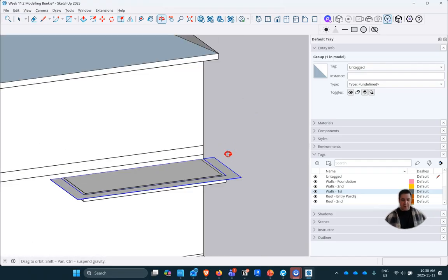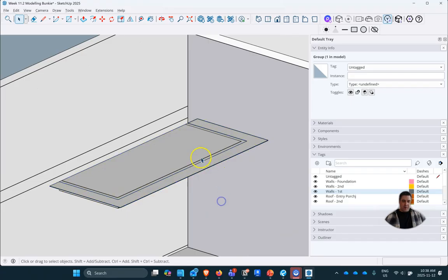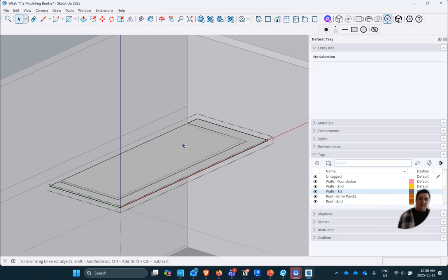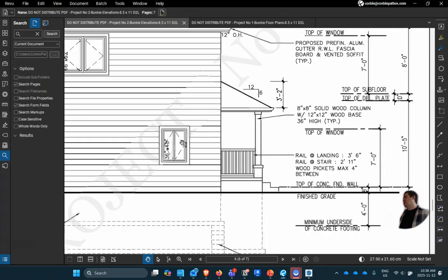So there's our roof. And so let's now work on the pitch. So let's edit our piece here. And so we have a slope of some sort. And I think the normal assumption is it's probably going to be the same, the 5/12, but if you actually look at the drawings, it's not. So we have a 6/12 pitch here. Honestly, I don't know why they decided to do this. I'd probably just keep it the same, but for all intents and purposes, it's different, so let's make it different.